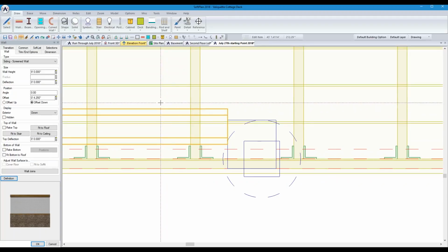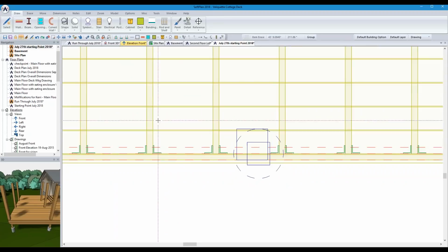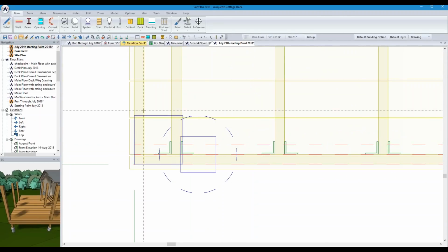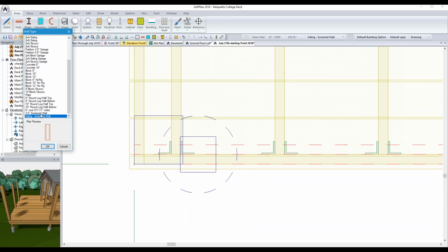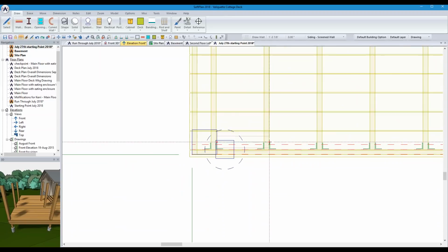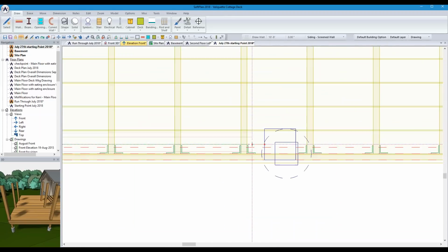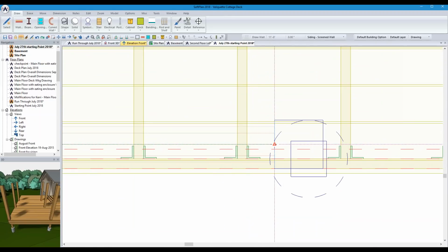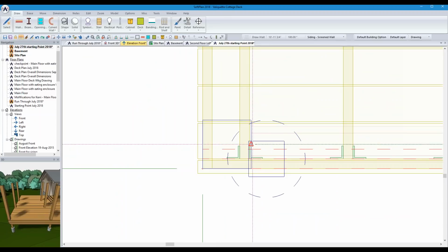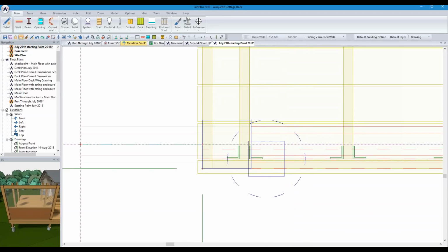And I'm going to erase the one that I have there. I'm going to show you what happens now when we trace this with it set to the center. So if we were to go to Draw Wall, pick it again, make sure that we're drawing it. And this time I pick here, and I zoom back in over here. Okay. Clicked incorrectly there, sorry about that. Click to the outside, and now we have our wall showing there.